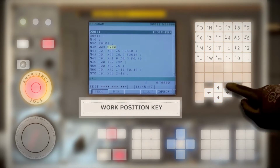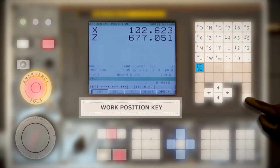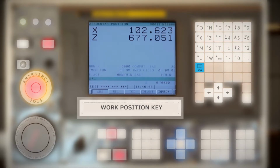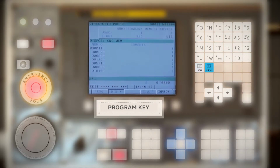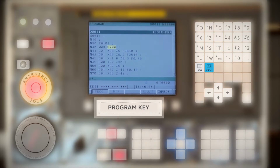We have the position key, which shows us the coordinates of the tool with respect to the 0 of the piece or the 0 of the machine, depending on which coordinate system we have set. This is the program key, which enables us to view the program to use, the list of programs loaded in the CNC, and, if applicable, the CNC mode activated. Edit, rename, and delete them.